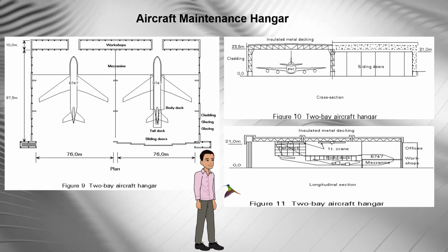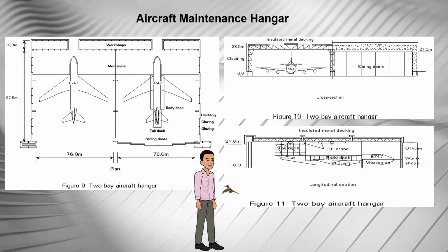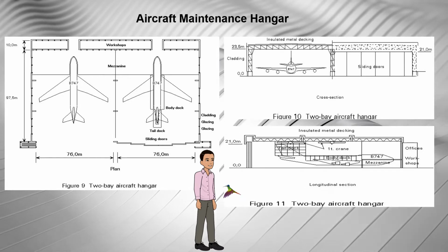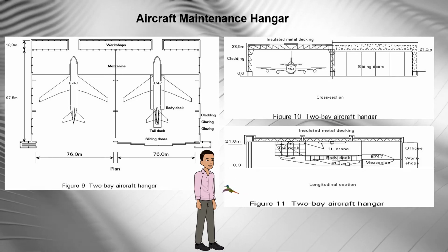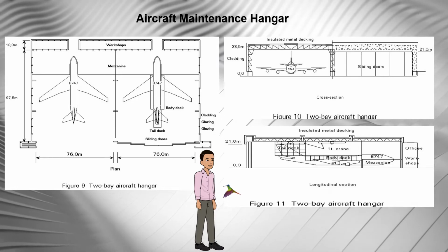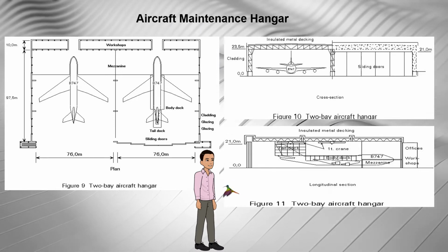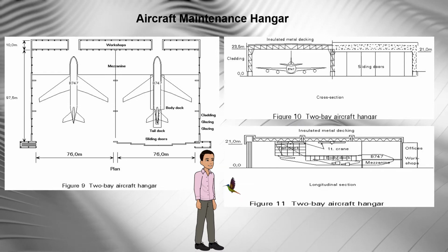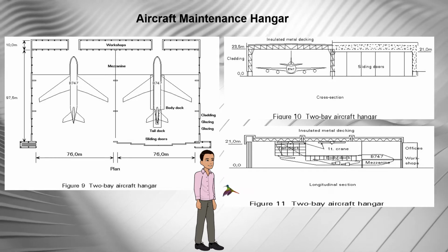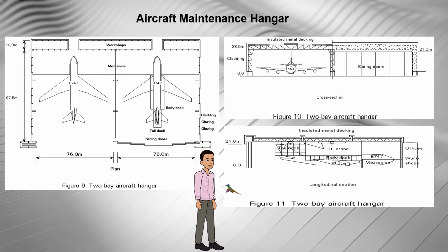While some smaller hangars have been constructed in pre-stressed concrete, virtually all are now constructed in structural steelwork with insulated steel cladding. Hangars are specialized for maintenance of one type of aircraft or mix of types. Access to an aircraft, because of its shape and size, is a problem which is best solved by specially designed docking tailored to suit the particular aircraft.